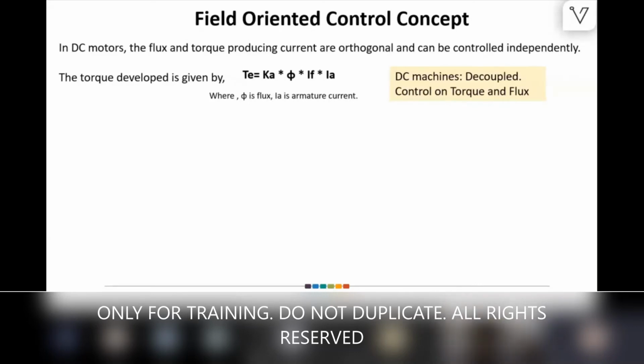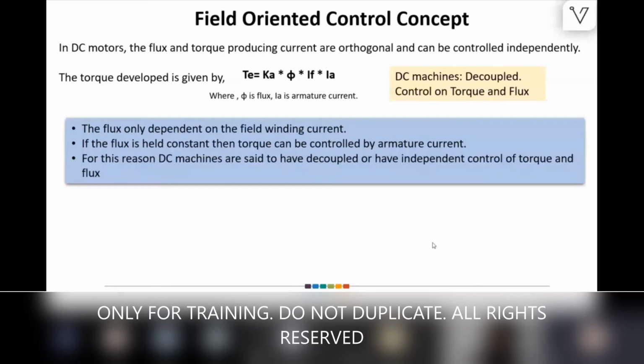Now many people will say BLDC, is it a DC? No, it's not a DC, it's an AC. When I say DC, a DC machine is one where we have brushes and a commutator and all those things, right? We can't use those kinds of machines here, even though they are better for control. Here we need BLDC or PMSM. BLDC may be a low-cost machine for maybe a two-wheeler, but for PMSM and IPM machines, these are the control strategies that we have to implement.